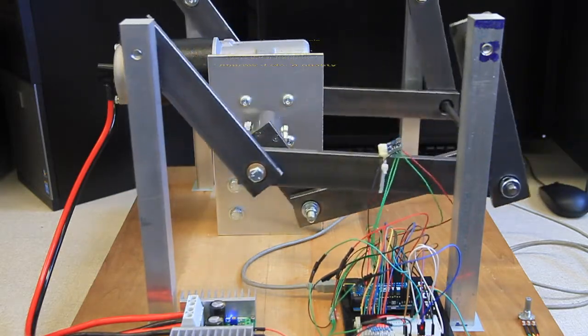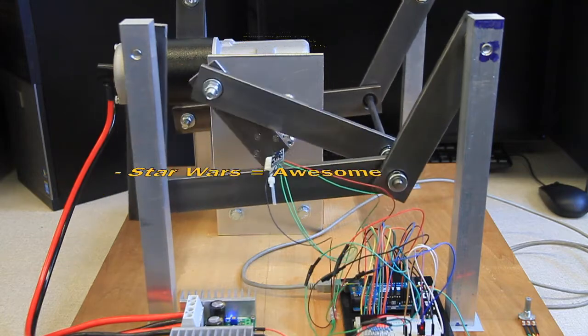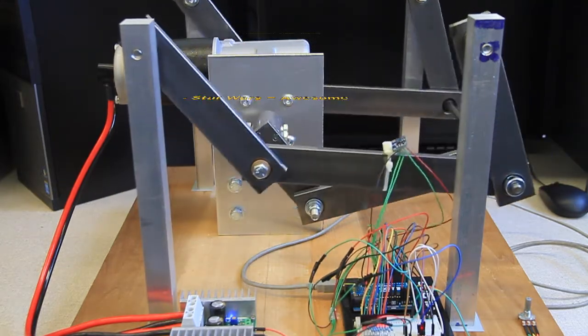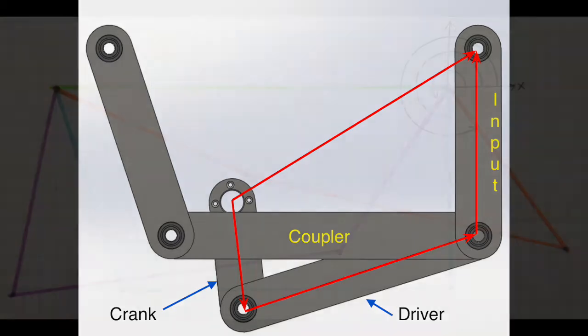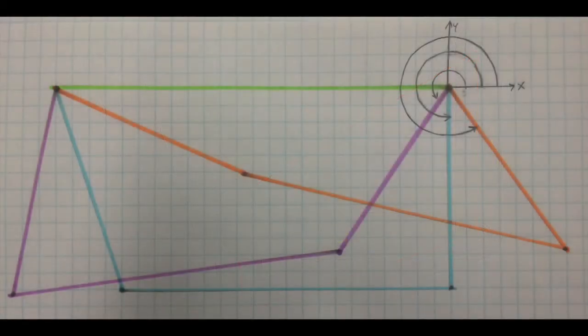In order to provide this functionality, we evaluated geometric concerns and chose regulatory movement variables to define the desired rocking motion. One of the major goals of the project was to create a mechanism that oscillates from one extreme position to another with equal timing in both directions and a constant input speed of 22 RPM. The input link was constrained to move no more than plus or minus 35 degrees from the negative y-axis.